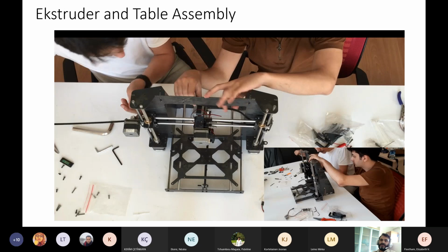If you notice here, there are two guide shafts in the X and Z axis movement of the extruder. Although precise and accurate motors are used for axis movements, we will need to provide structural rigidity to ensure axis movement accuracy. For this reason, these guide shafts provide structural rigidity.